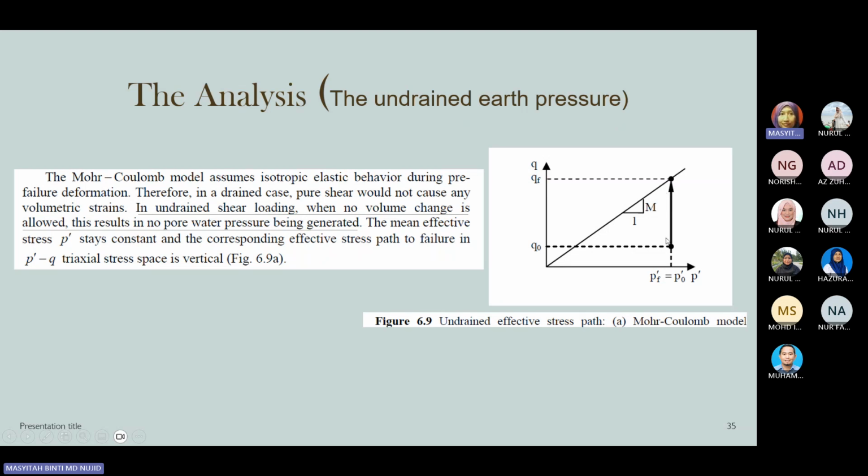So when we have this kind of high value of undrained cohesion, it says that the structure is safe. However, in the real conditions of soil at the site, it is not truly what we have designed. So when you have these kinds of problems, it's better to recheck, redo, and redesign based on real-time data, so that we can have some sort of early warning sign or early mitigation to ensure our structure will be safe during the construction time or after a few years of construction.